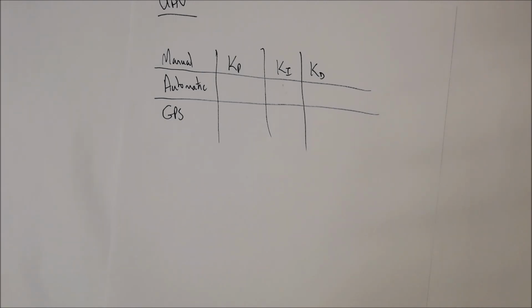I don't program them as hard code in the equation itself, but as variables, because then it's easy just to change these variables and to increase and decrease them. And then from that, you're able to monitor the outputs, maybe monitor the speed of the motors, and see how it performs. You can even plot these graphs if you want to. And then you can adjust these values and tune them to the desired values that you want.